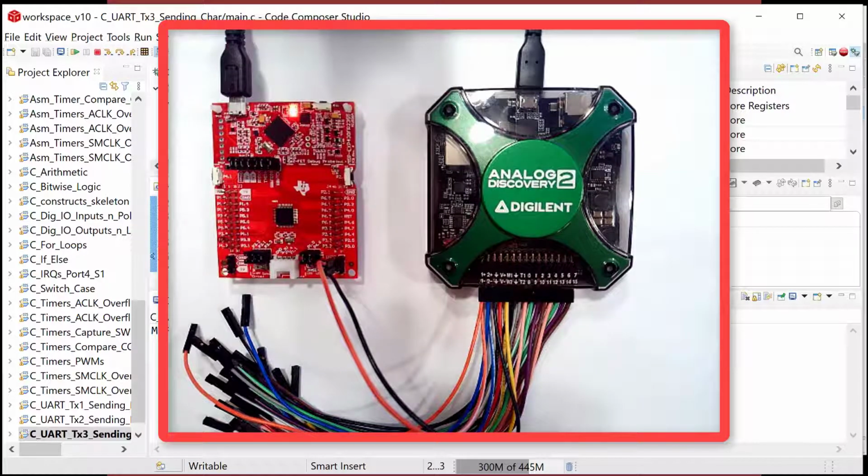Well, the way that it works is that a computer has all these ports that come in, and we already saw that this comes in on COM5, I believe it was. So you can have applications on the computer that will open up that COM port and send UART information back and forth. What's good for us is that we can use a terminal application on the computer and receive the ASCII characters, and it will display it as a letter, or you'll see capital A.